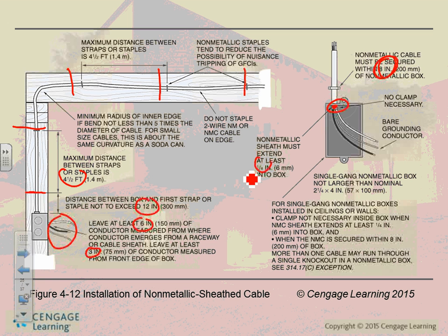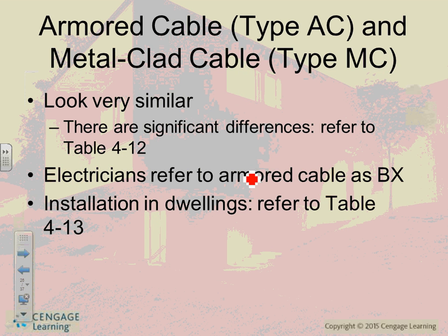It will be different depending on how big the box is. So typically, if you measure from here to here, 6 inches, you're good most of the time for all cables. And at the end, from here up, you will leave 3 inches for what? Termination. So if the box is deeper, do you end up with more conductor? Yes. Okay. So these are a few rules, guys, about Romex.